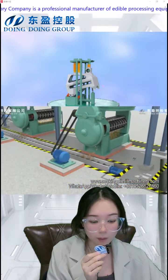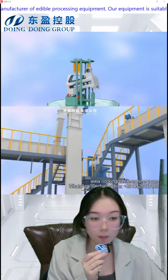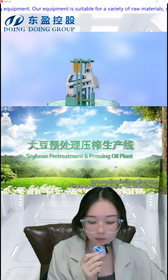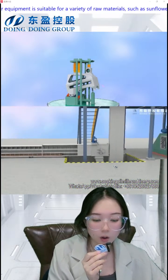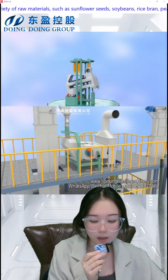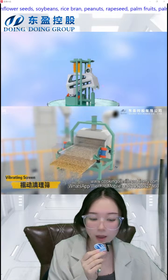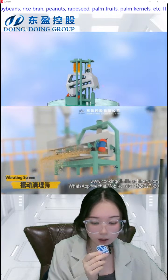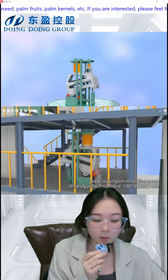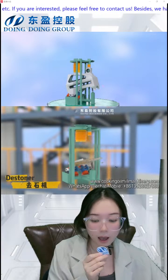Why did we choose a round roll oil press for our small oil press? Mainly because it is designed to be more wear-resistant, which can greatly increase its service life. There is another type of oil press, which is a strap press. Although it presses oil under greater pressure, it also causes high wear and tear on the machine, and the maintenance cost is very high.